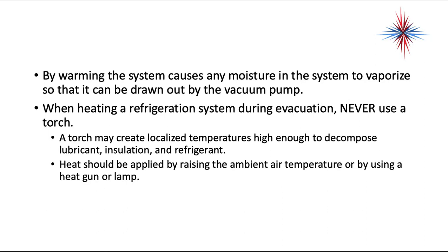When heating a refrigeration system during evacuation, never use a torch. A torch can create localized high temperatures enough to decompose lubricant, insulation, and refrigerant. Heat should be applied by raising the ambient temperature or by using a heat gun or lamp.